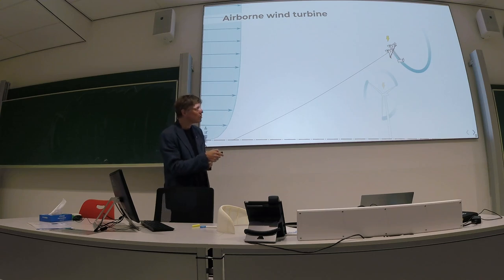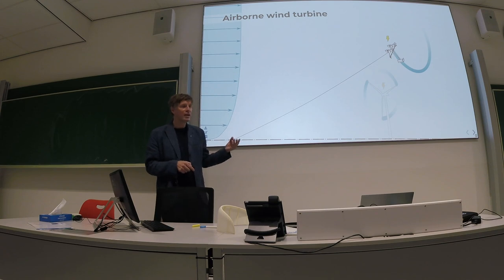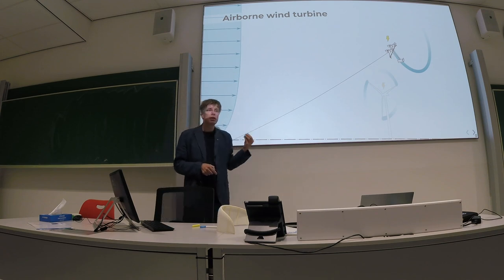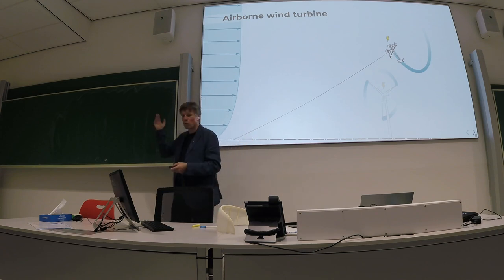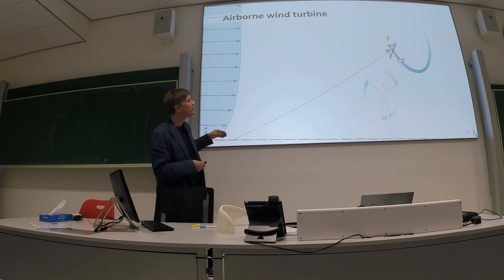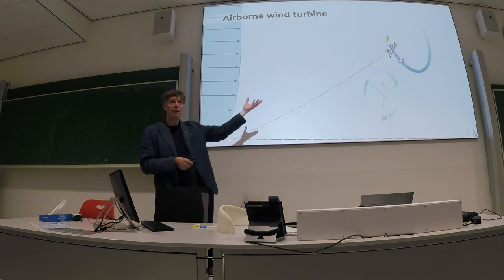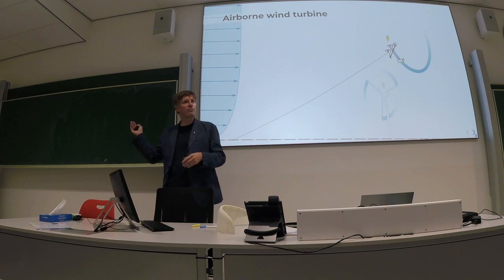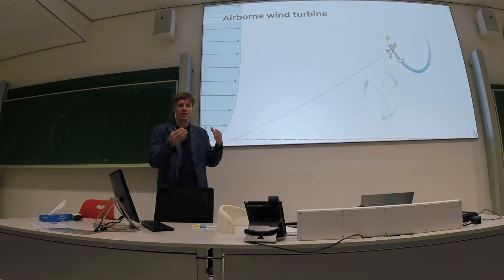Like also the kite has aerodynamic drag, and the more drag you add, the slower the kite will fly, obviously. We'll get to the theory later. When the kite flies slower, you saw from this formula, the apparent wind speed gets lower and the performance will drop. So drag is always negative.